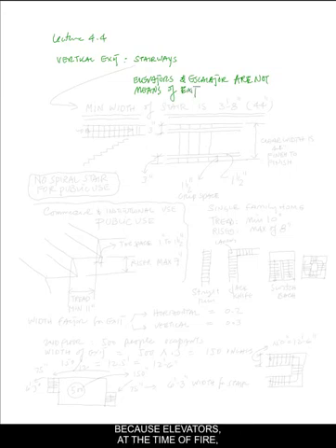because elevators at the time of fire will act like a chimney, and the fire and the smoke goes through it, and therefore the person inside the elevator will not survive. And the escalators are within an open space, and the steps within the escalator change as the escalator moves up and down or gets close to each landing. Therefore, there can be complete confusion by people who are traveling through the escalator when it comes to a halt for a particular reason. So solid stairways are the way to go.